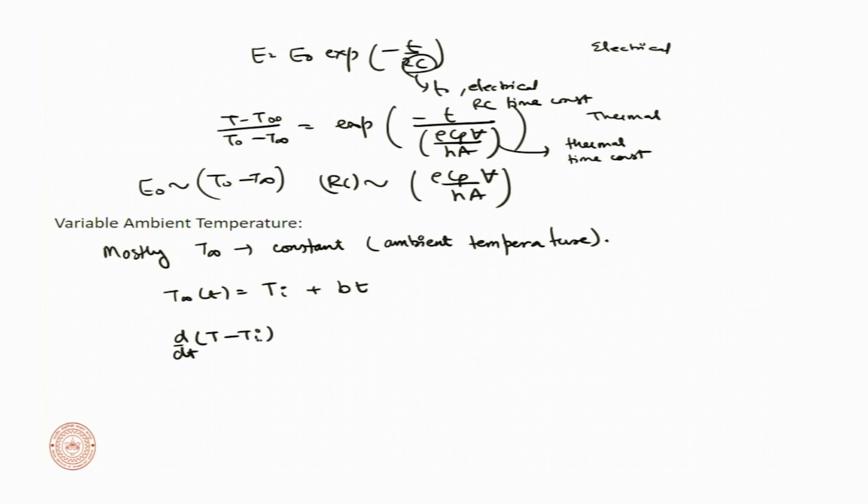We are changing the variable. This is a change of variable basis, right. We are replacing T - Ti with minus (T - T infinity) over alpha star. Alpha star is not thermal diffusivity, it is a combination of rho Cpv over Ha.